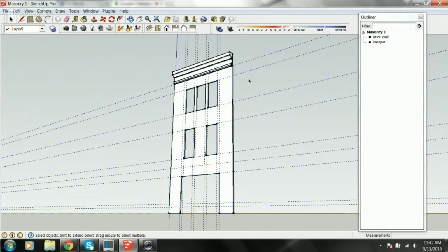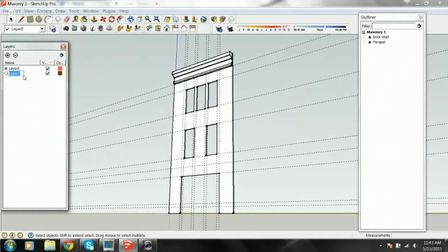Okay. Well, that's what laser cutters use, because they have an etch burn and a cut burn. Right? Well, I think the way to do that would be to get into the layer dialog. That's just for the future. Add a layer, and you can see right there: cut, etch, whatever it is. Let's just do this, because that way you've got it for reference. I've got a new layer here.